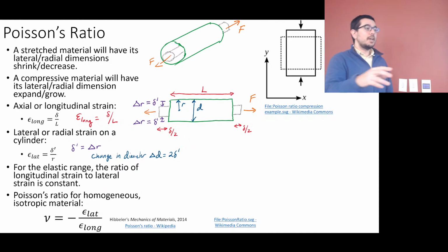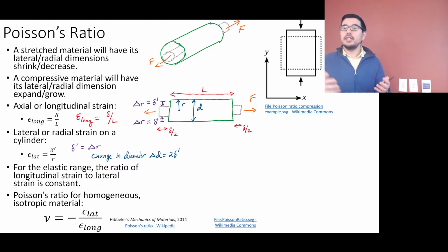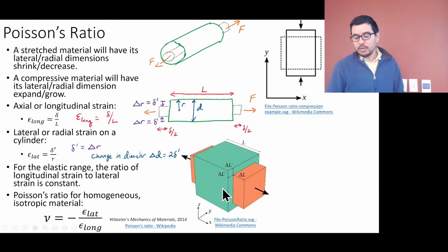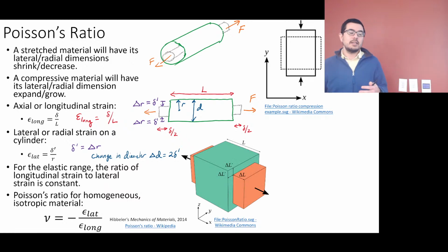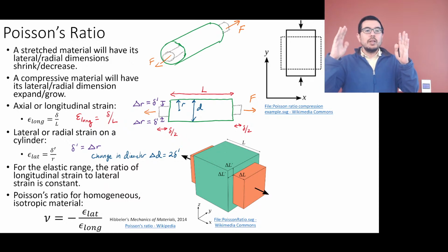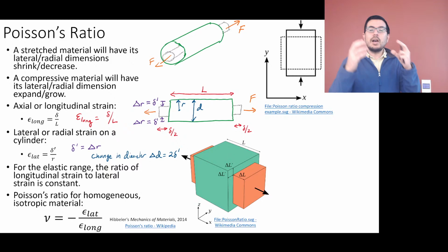And there's some good videos. At least, I didn't make them, but the ones that I posted from the Efficient Engineer and some of these others, they're pretty good. They explain this concept very nicely, and they even talk a little bit about the auxetics, okay, which are materials that have a negative Poisson ratio. Okay, so these are kind of engineered materials, right? So like little boxes put to each other that buckle, so that when you actually compress them, they don't expand. They actually kind of collapse a little bit. Okay, so the ratio is opposite of what you would see in a normal solid.